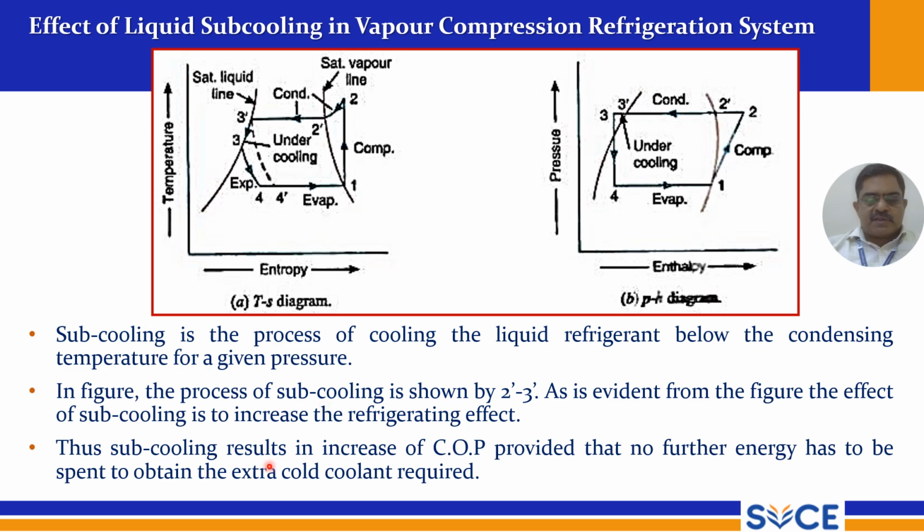The subcooling results in an increase of COP, provided that no further energy has to be spent to obtain the extra cold coolant required. So subcooling is actually a desirable process. It increases the COP provided no further energy has to be spent.